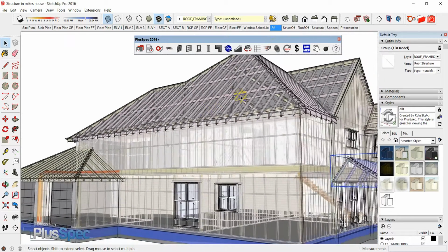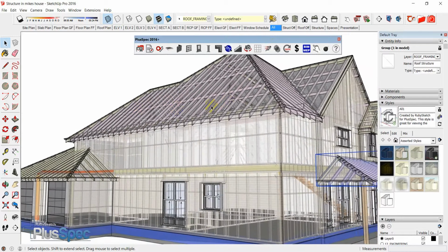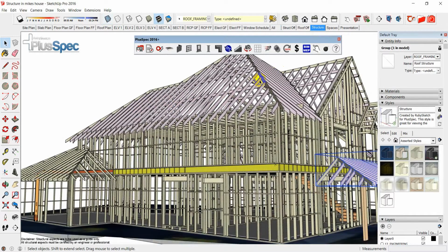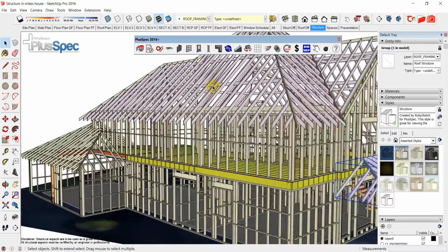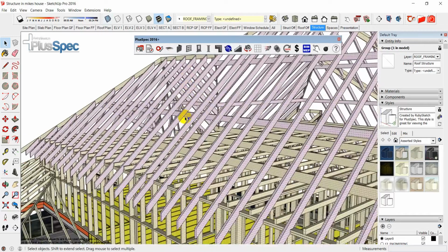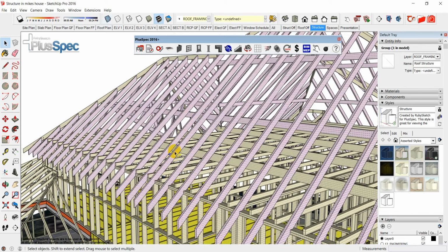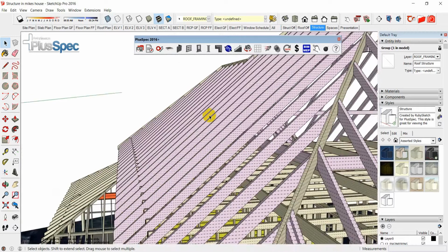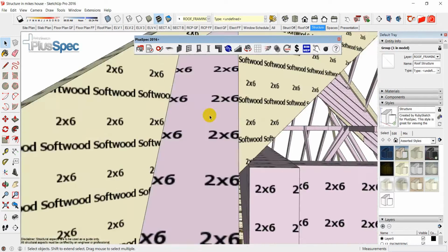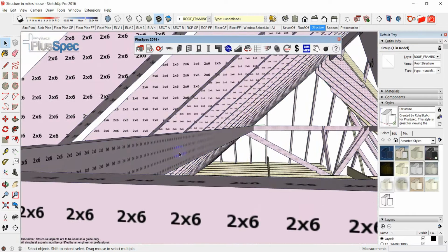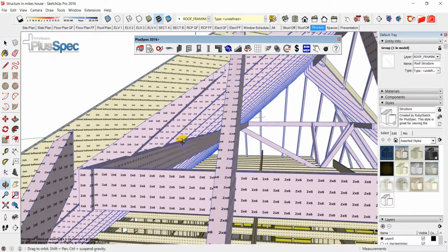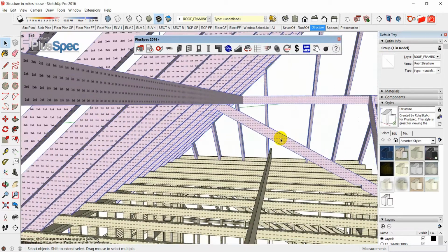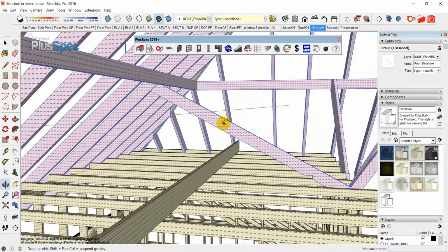Now inside of the roof, you'll know we have these things called under purlins. If you're not sure what they do, let's go and have a look. Essentially, these timbers have a span that they can go to, and you can quickly go to Google and find out what the span of a particular rafter is according to the weight and maybe the location that it's going to be placed. In this case, these rafters will only span a certain distance, so this under purlin has been put in to hold the weight of that. And then we would use something called a strut or a scissor strut that would distribute that load down to a load-bearing wall.